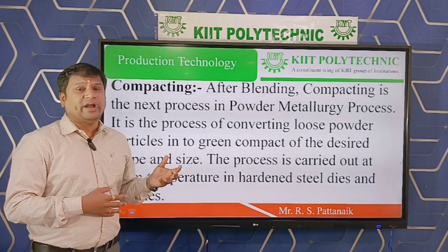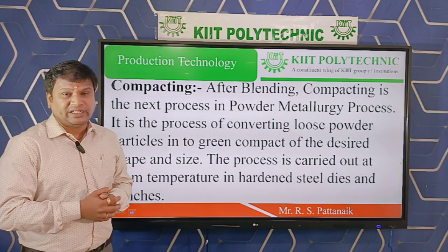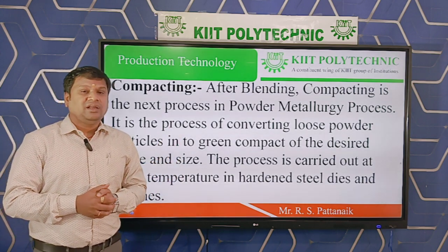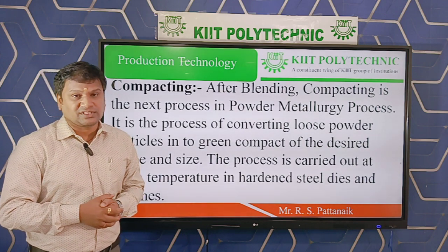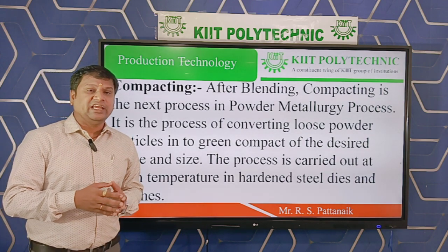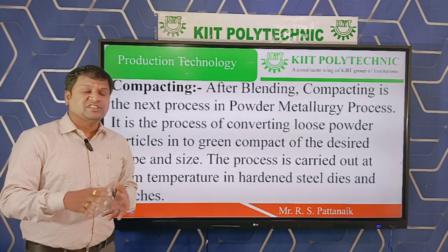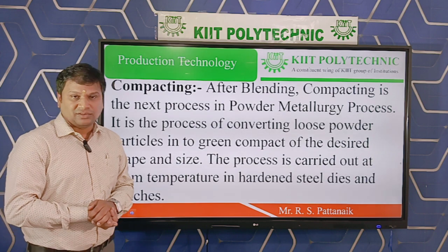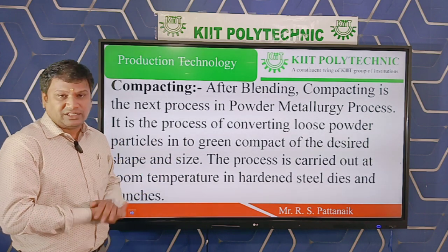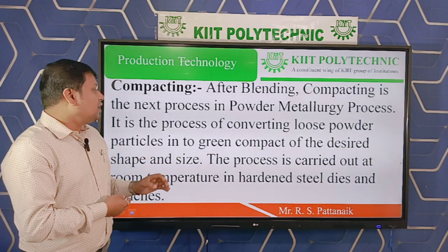The pressure required for this compacting is generally 80 megapascal to 1600 megapascal. Both mechanical and hydraulic means are used for creating pressure in this compacting step.